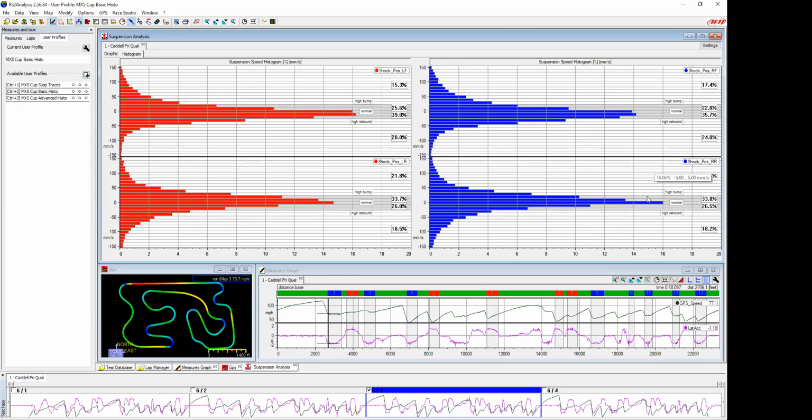We have to dig into why, but that one there is showing that right rear is staying at that neutral position a lot, right? Maybe that's telling you something. Maybe there's a slight bent shaft on that one, or the seals are bad, or something in the suspension is binding it up. Just that's how you start to read these things.